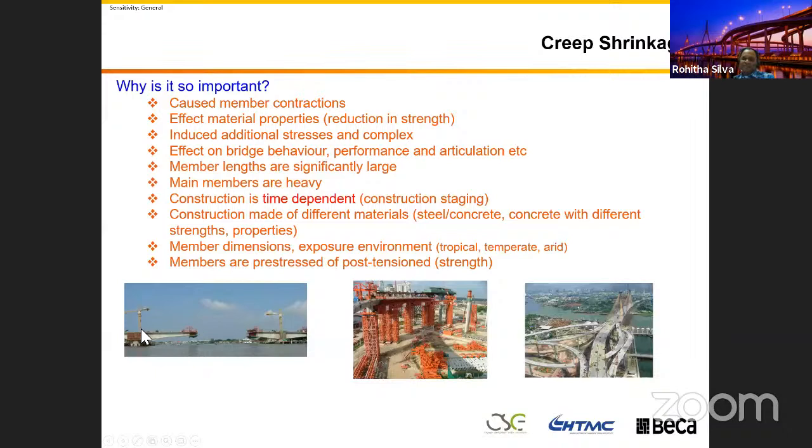We build these bridges with the upward camber and let the bridge deflect downward. But when you are constructing these long span bridges, it's never going to work that way. And the effect on bridge behavior, performance, and articulation, the creep and shrinkage will affect that.